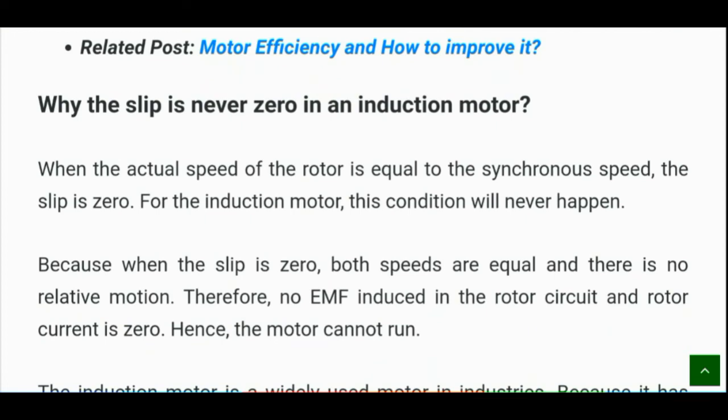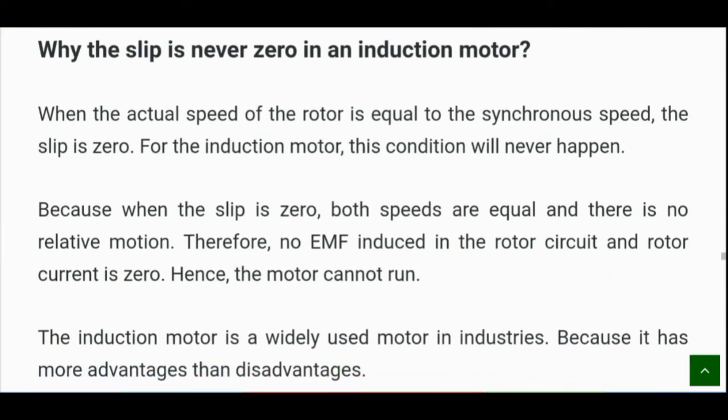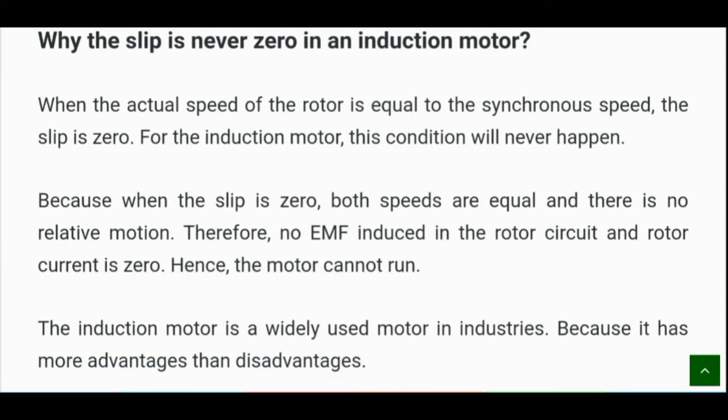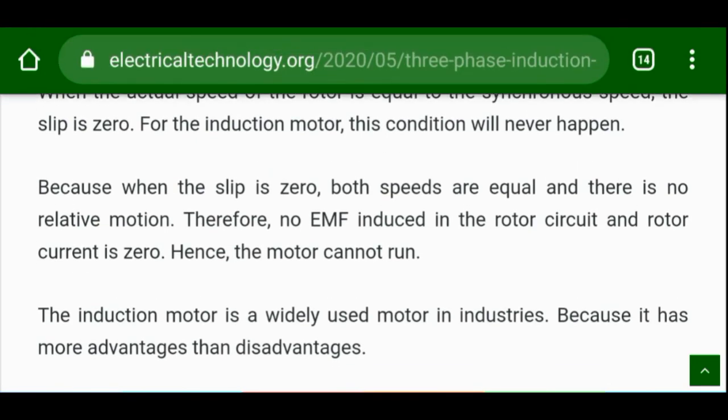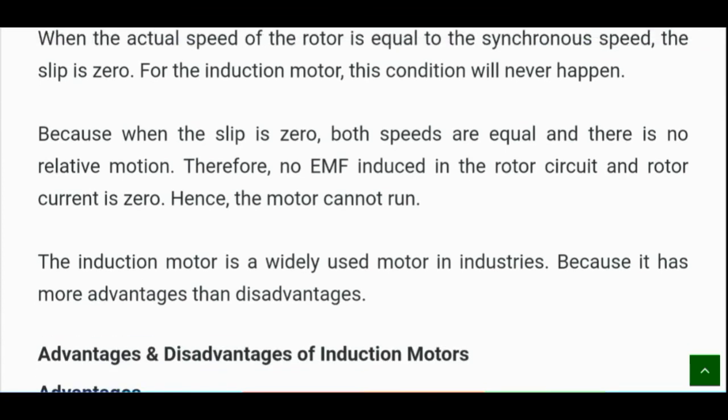So why is the slip never zero in an induction motor? When the actual speed of the rotor is equal to the synchronous speed, the slip is zero. For the induction motor, this condition will never happen, because when the slip is zero, both speeds are equal and there is no relative motion. Therefore, the EMF induced in the rotor circuit and the rotor current are zero. Hence, the motor cannot run.